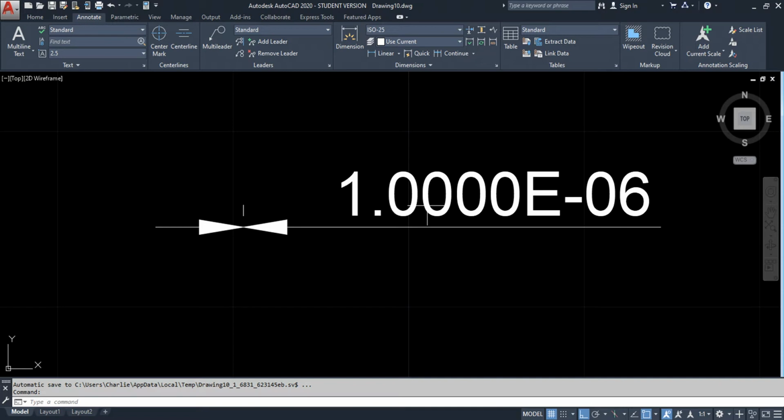Okay, so whatever input you get, you change the input value and create the drawing and take the output what you want. If you have a metric input, you create the drawing in metric and take the output in inches. So it's easy for you to convert here in AutoCAD.